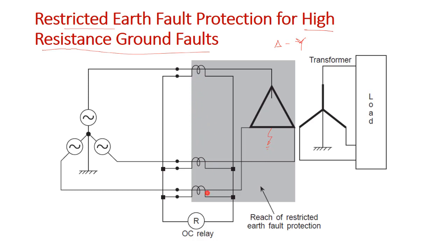make such an arrangement, like we put a highly sensitive overcurrent relay by connecting the CTs in star fashion and connecting finally to the overcurrent relay. Whenever there is a winding to core fault, only under that condition will this relay sense the fault current.